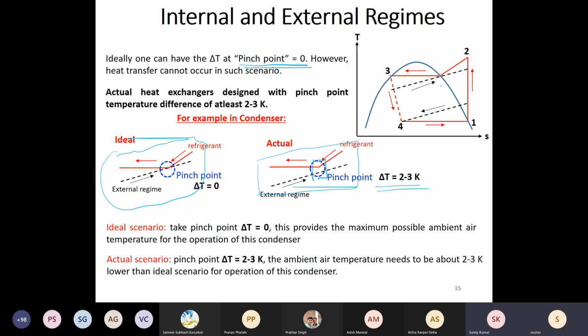Okay. Which type of heat exchanger have I assumed in all this analysis? Parallel, counter, cross? Counter. So this is still the best case scenario. And now think of the actual heat exchangers which we have. They are not even counter, they are cross. So they work with much larger delta T's.